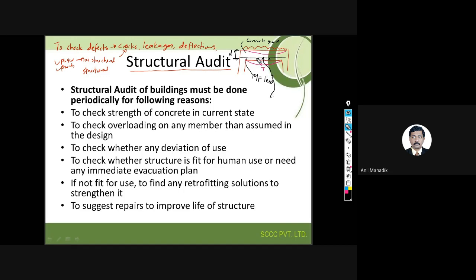First, you will see that the structural cracks are in the maximum bending moment zone, and you understand that by structural engineering philosophy. And their crack width is greater than 0.3 mm, even 1 mm may be there. If there are very wide cracks, you can say it is a structural crack, and then you need to give solutions for that. So you can identify that.